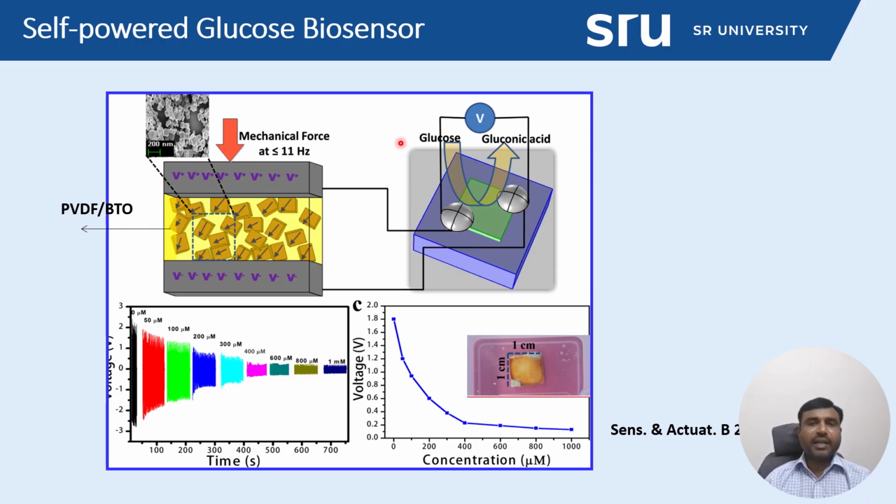For example, here we developed a nano generator, which is a very thin film on a flexible substrate. After fabricating, when adding glucose, it converts the reaction without applying any potential, because it itself generates a potential when applying a physical pressure or mechanical force. The voltage developed through the mechanical force is sufficient to oxidize this reaction, without any external voltage or current.